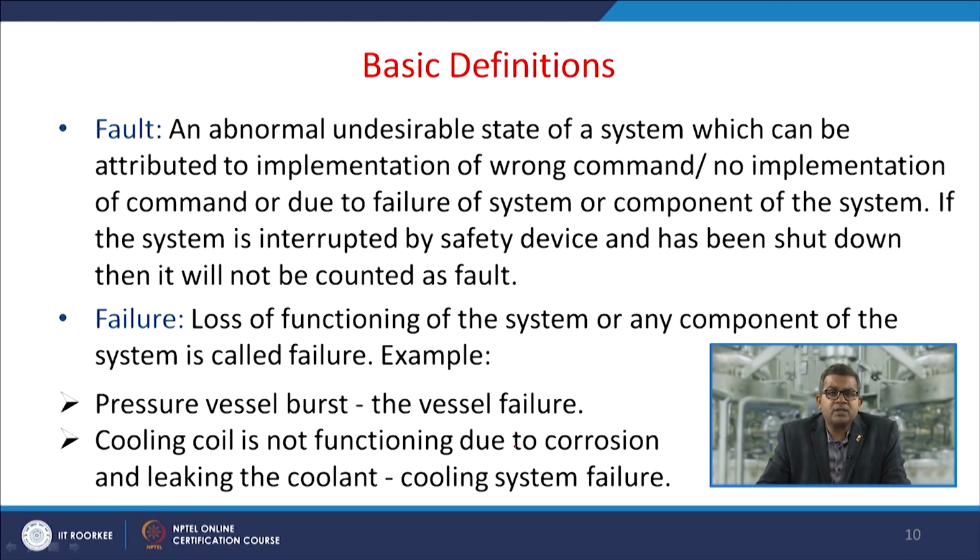Another definition is the fault. What is the fault? This is an abnormal undesirable state of a system which can be attributed to the implementation of a wrong command, or sometimes with no implementation of a command, or due to failure of the system or a component of the system. So if the system is interrupted by a safety device and has been shut down, then it will not be counted as a fault, because this is a deliberate event.